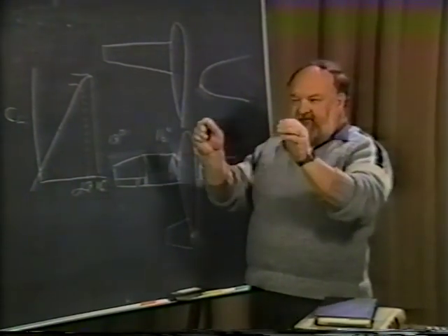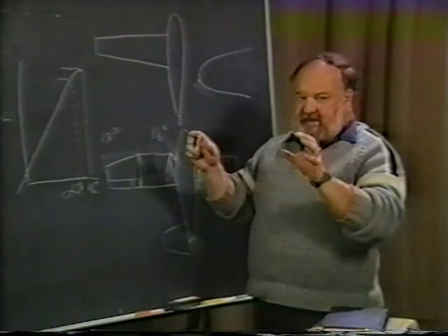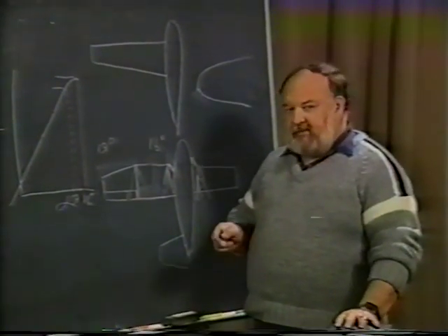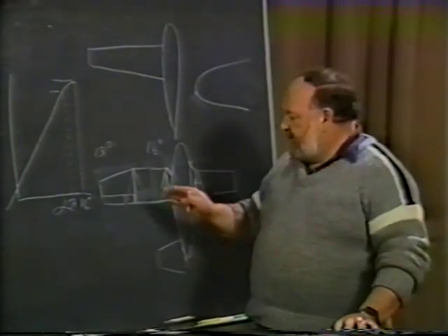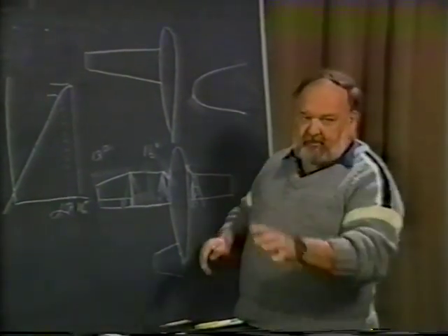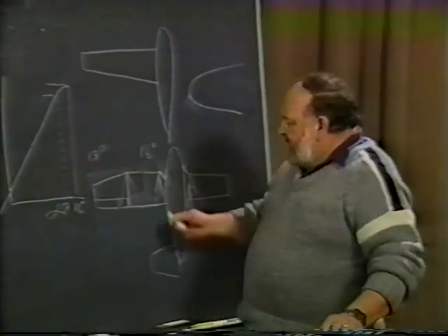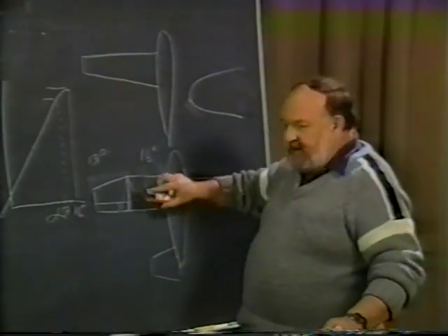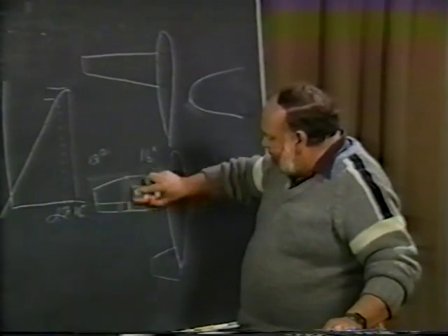and therefore to have both wings stall exactly at the same time is not that easy of a thing to do. And many times, with just a little bit of yaw to it, one section will stall first, and that means the airplane will start to roll. So something nice inboard is a good approach, trying to stay away from something outboard on the thing.